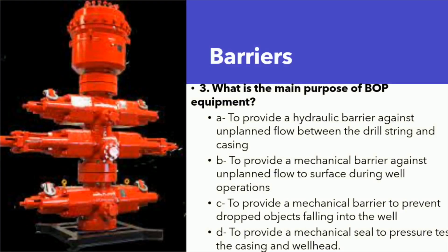Barriers. 3. What is the main purpose of BOP equipment? A. To provide a hydraulic barrier against unplanned flow between the drill string and casing. B. To provide a mechanical barrier against unplanned flow to surface during well operations. C. To provide a mechanical barrier to prevent dropped objects falling into the well. D. To provide a mechanical seal to pressure test the casing and wellhead. The correct answer is B, because a BOP is a mechanical way to prevent flow from the wellbore to surface.